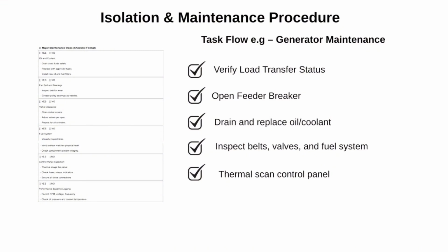Run a load test and log all readings. After maintenance, you want to make sure the generator can handle real load. The MOP should include expected ranges for voltage, frequency, coolant temperature, oil pressure, whatever's critical for that site.